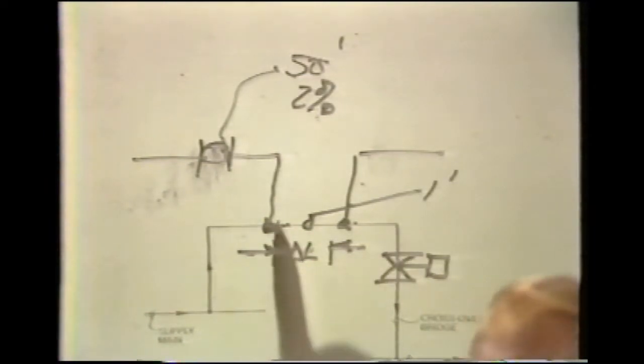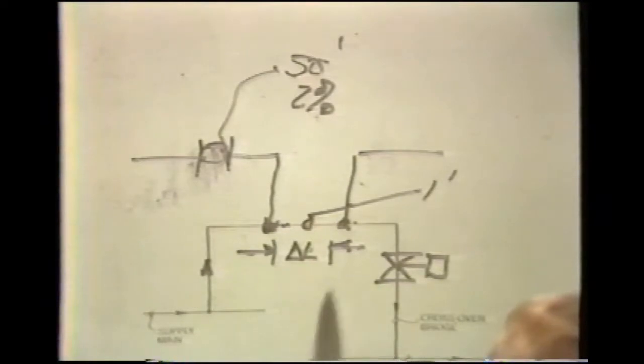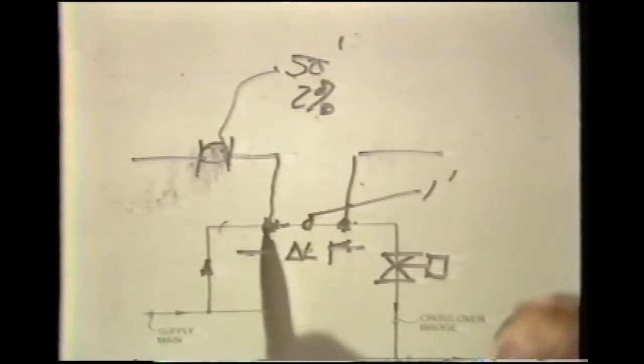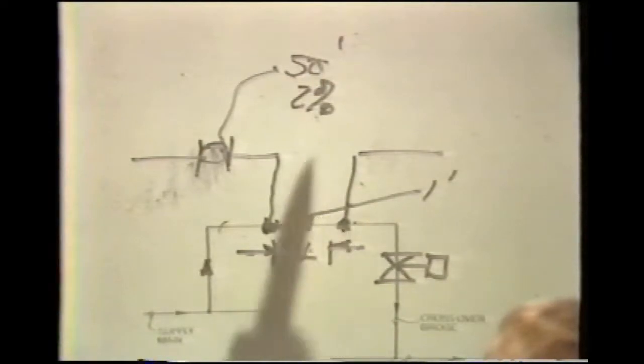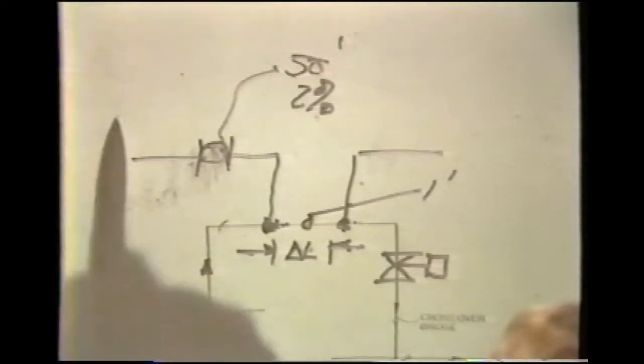And inasmuch as the common piping is generally sized to the pipe size that we have in the crossover bridge, this means that we can allow a relatively substantial length in the common piping, providing the secondary circuit pump operates continuously as it would in a system of substantial size.